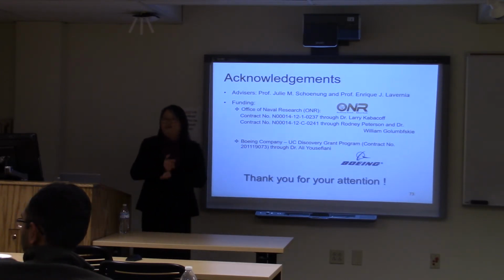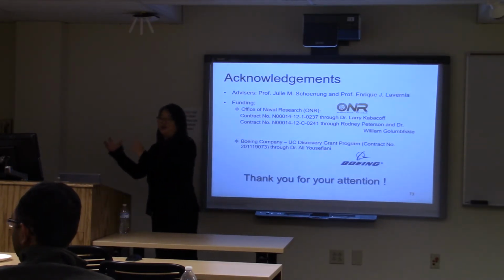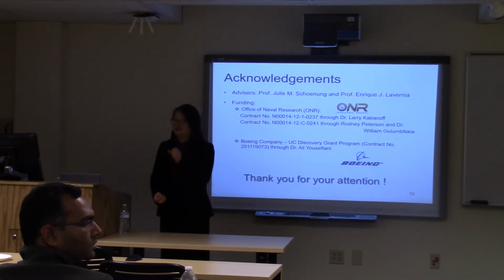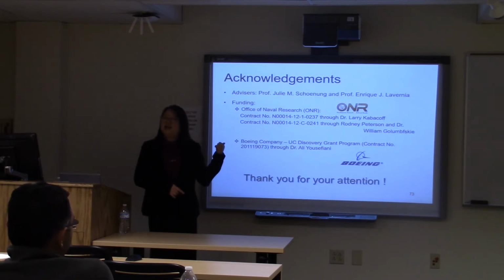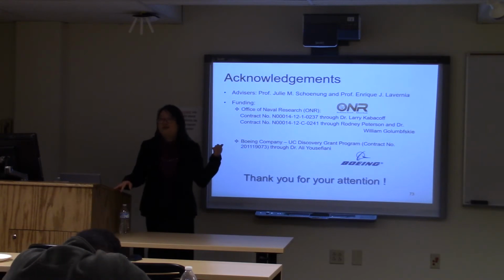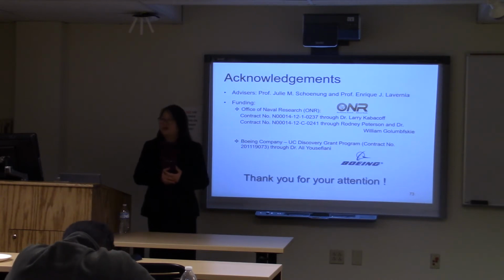So we have two resources. First, our group has an in-house gas atomizer. So we can just buy chunks of materials, make the right alloys, and then use the atomizer to produce the powder. Second, like the engineering materials I have studied, because they are already available commercially, we can just buy them. And those are less costly than making them. But there are some special alloy compositions that we made in-house.